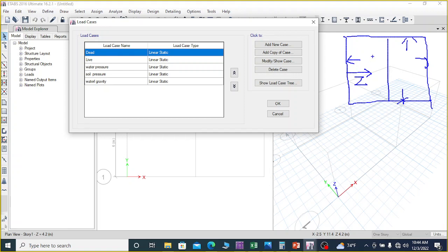So to make this consistent, the direction of the soil pressure is in the opposite direction of the water pressure. So we have to make the factor of the water pressure -1, because the water pressure is acting in the negative z direction. So I have to adjust the local z in this way.